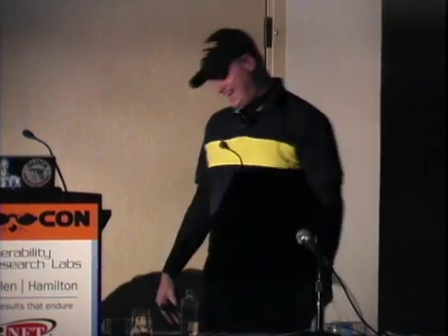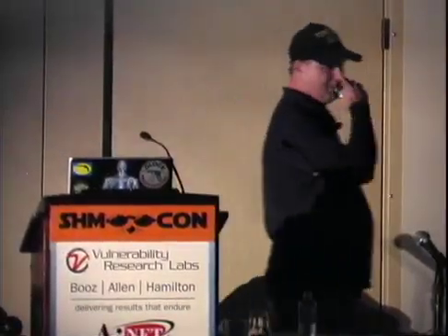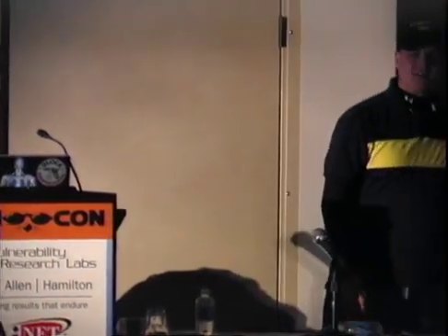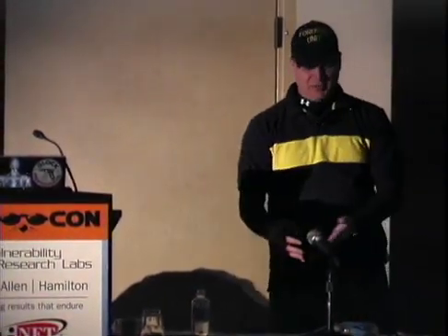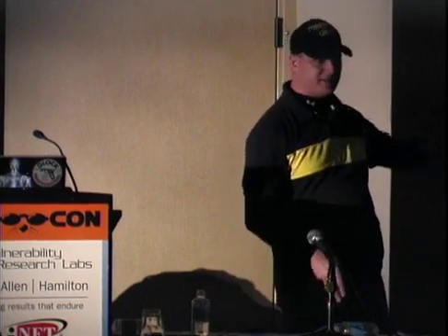Here's another thing. If you rip these off, don't plug it back into that power supply. That's probably the end of your drive. You will cause it to not spin up again, and you've just fried the damn thing. You're going to blow the preamp on the head assembly or something. So plug this into something else, something a little bit better on your workbench, to at least make sure that you can read this.